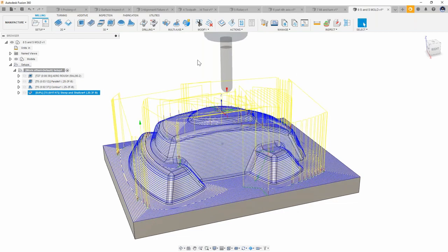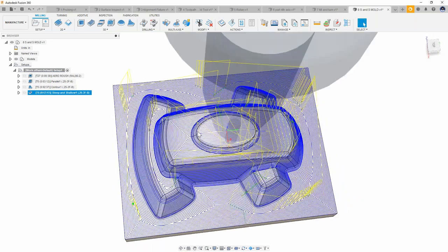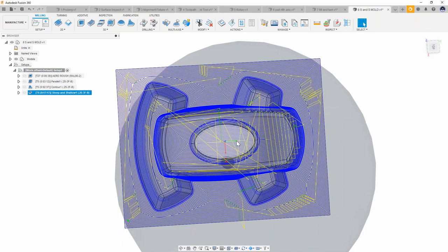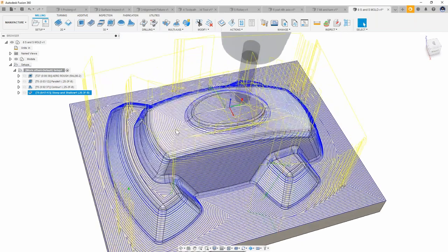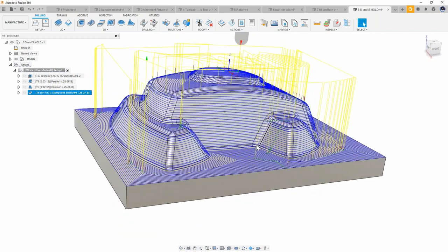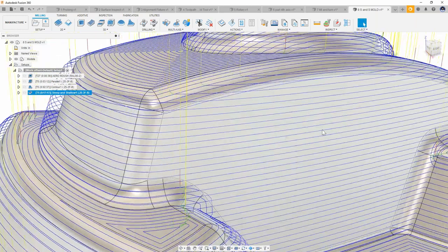Now I'm gonna set these passes to be a little wide, so we'll set these as 30 and put this one as 30. And I'm just gonna hit OK. Now, again, like I said, that's my favorite method for generating 3D toolpaths because I don't have to change 100 different things and then figure out why it didn't work. So that looks pretty good. Now we can see that this is doing kind of the best of both worlds. It is striping and getting me a good toolpath here. I'm not a big fan of some of these breakdowns with scallop and the way that steps over, but this is at least covering the entire part. And if we look at this a little bit closer, we can start to identify the different strategies here.